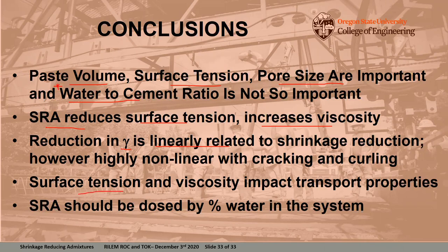Surface tension and viscosity can dramatically impact transport properties, and we have to be very careful when we bring these into service life models, because they can dramatically extend the service life of a concrete structure.